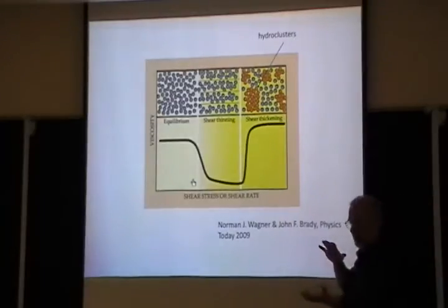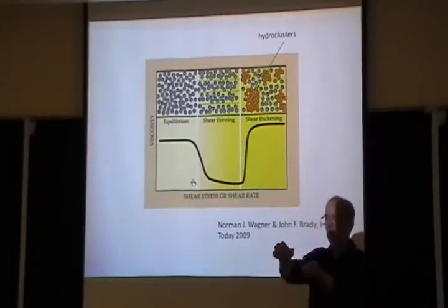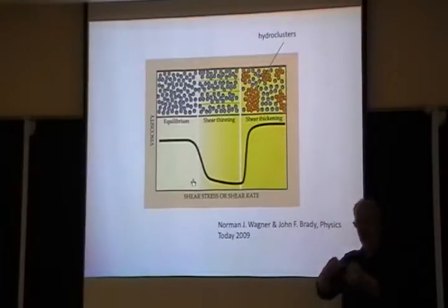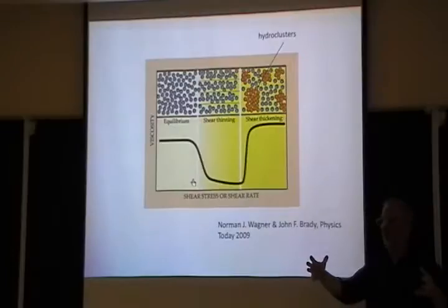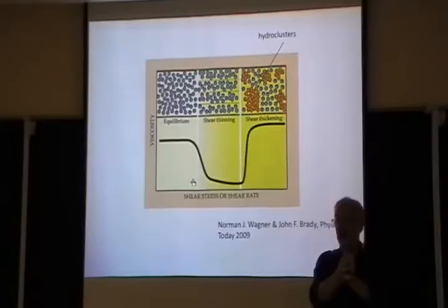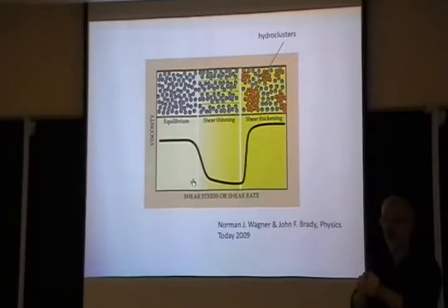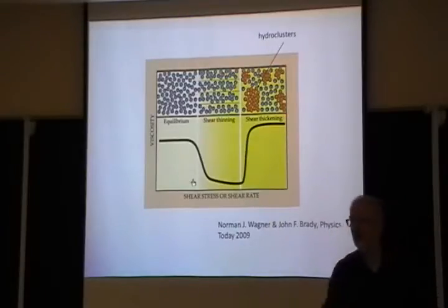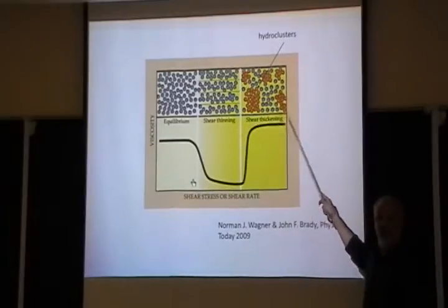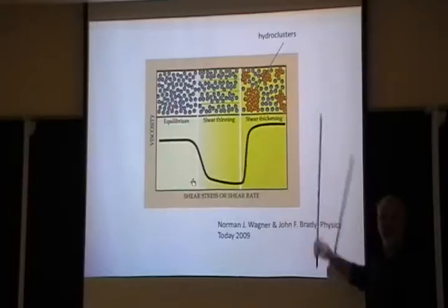But then, at some point in shear rate, this thickening emerges, and it is basically the following idea, that the shear rate shoves particles together, and then Brownian motion, for example, allows particles to diffuse away from each other. And if the rate is large enough to shove them together, then lubrication forces will be large enough to bind them together until finally Brownian motion pushes them away. And you form these clusters. They are called hydroclusters. Right, so this is a Peclet number argument.